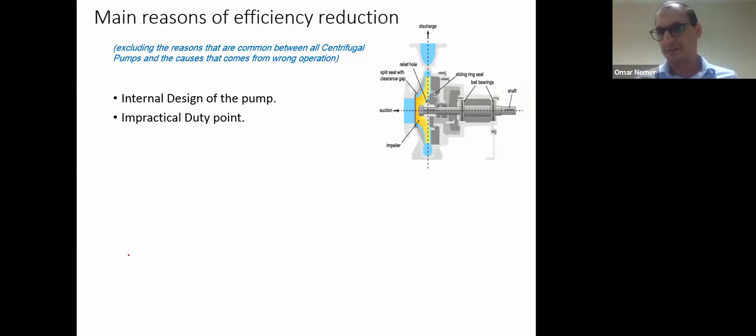You cannot find one. Even for any typical surface pump working on clean water, there are some reasons which can lower the efficiency. For example, the diameters will change between the inlet and the impeller inlet. There is friction loss inside the impeller, friction with the casing walls. There is some turbulence of water. There are some bubbles, whatever. All these reasons will lower the efficiency of the pump.